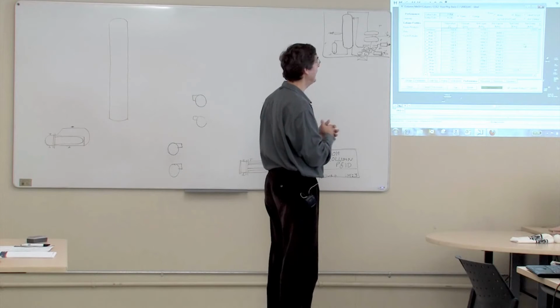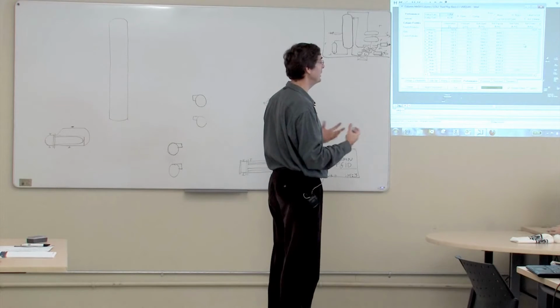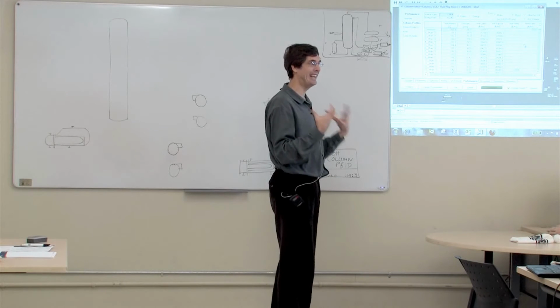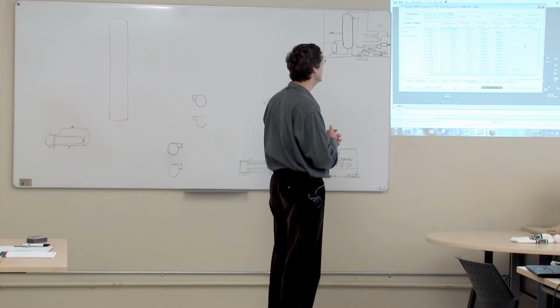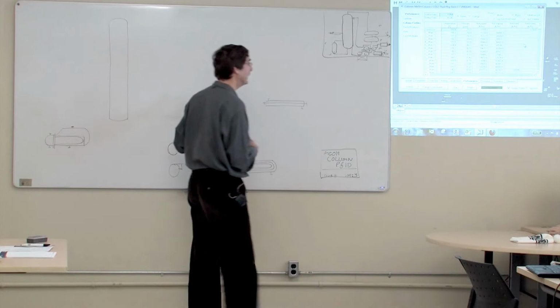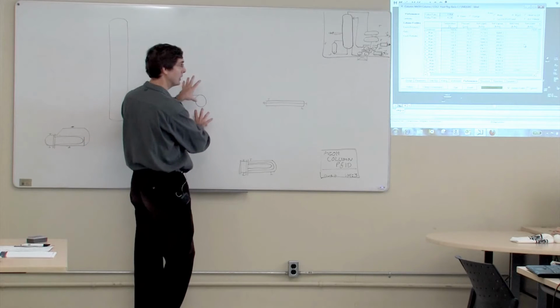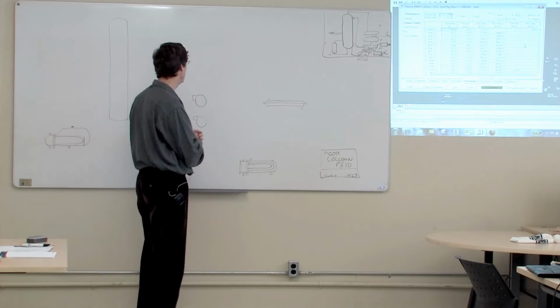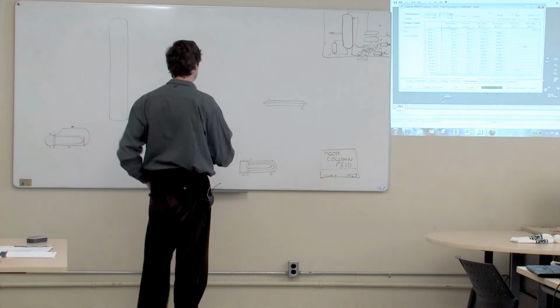So I think I'm okay just to put a single set of pumps for those two destinations in. That's my guess at this point in time, not having done the pump calculations that we'll get to later on. So I'm going to draw the P&ID with the assumption that I can do this with a single pump. We're putting two pumps in because of our spares policy, though. Does that make sense to you guys?